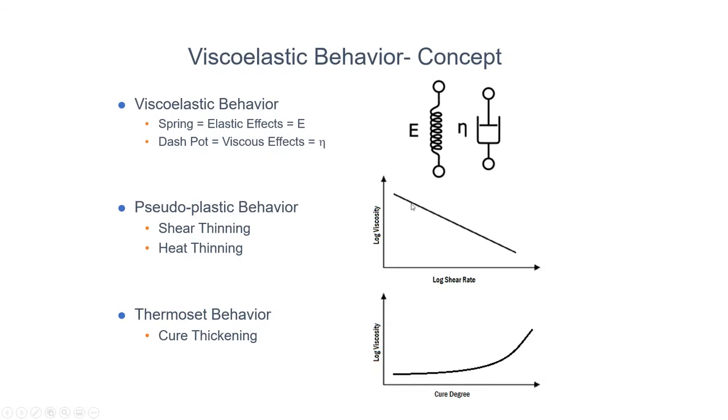And John Dick gives a great talk on why we can look at this as a straight line, as the power law in visco performance with respect to shear rate. And generally, we see all the rubber materials line up as a near or very straight line in ideal behavior, at least in certain sectors. Once we get past the Payne effect, where we have filler-polymer interactions, we see kind of a linear effect. And I'll talk about more of that as we get into this.